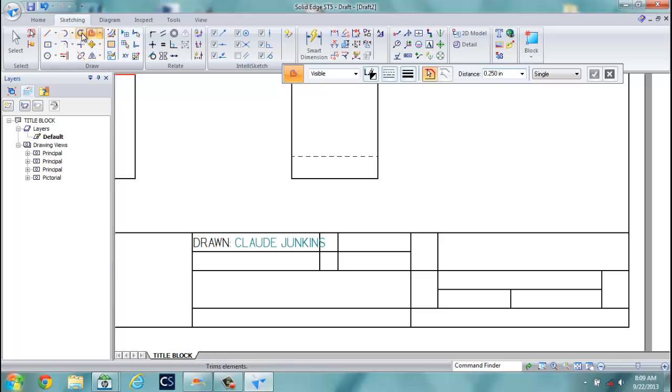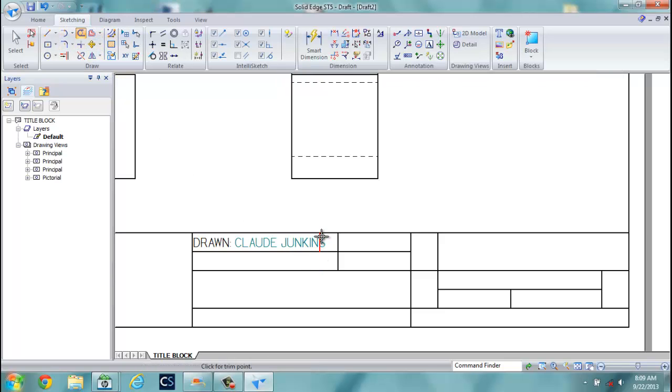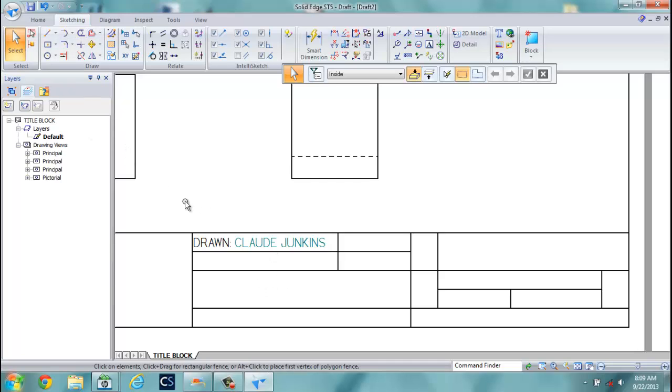And then I can delete this one. So you can customize yours a little bit just to make sure. Now if I want to, I can select this and move it down a little bit this way. What that's doing is picking up that information from the model that I brought in. R1 just refers to reference 1.